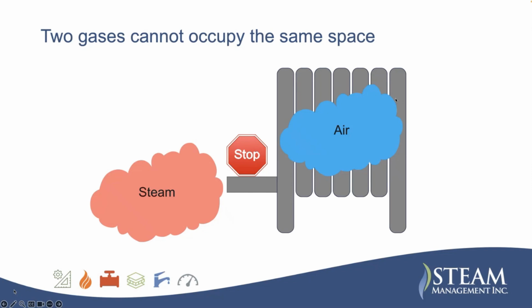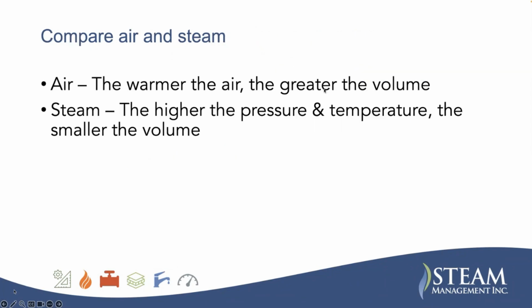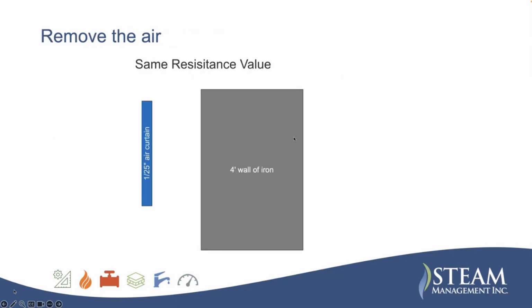Like I said, two gases can't occupy the same space. If there's air in a radiator or in a pipe or in a piece of equipment, I can't get steam in there. It won't leave. And one of the things that's a little bit confusing about air is the warmer the air, the greater the volume. But with steam, the higher the pressure and temperature, the smaller the volume. So it likes to mess with your head a little bit.